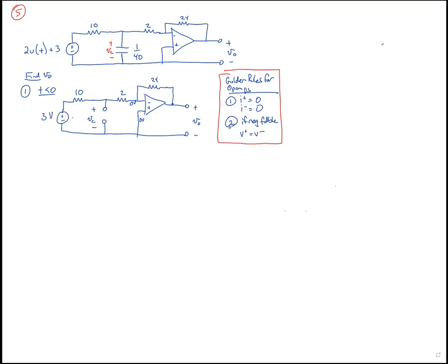All right. We're not sure exactly what's going on, but we can see that we're going to be using this 0 volt thing here. Whenever you get confused about op amps, always think about doing KCLs at the inputs. Never at the outputs, because you don't know what current's coming out of it, but you sure know what current's going into it. It's going to be 0.